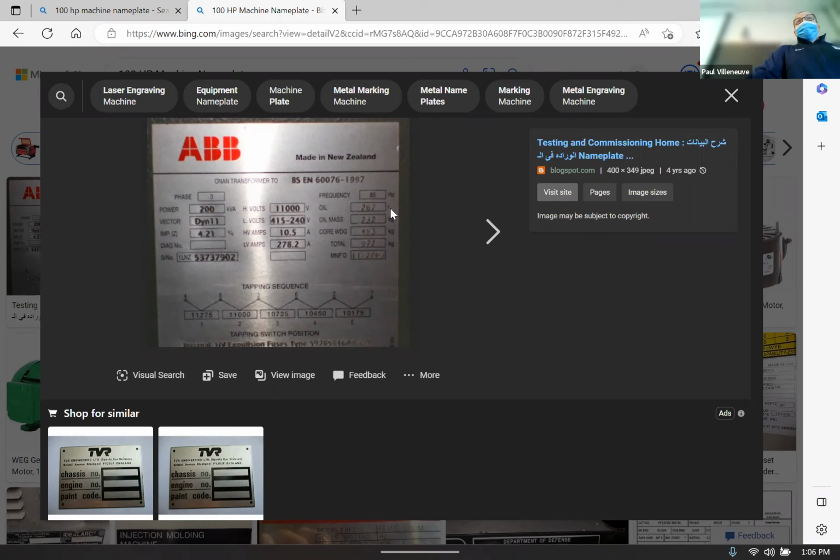Now, the other option is if you can get better cooling. If the room is not at 40 degrees C ambient, if it's at 10, then you can reject more heat into the room. As long as there's enough rejection of heat from the hot spot out into ambient, and the hottest spot where that winding is stays below the insulation class, it should run fine.